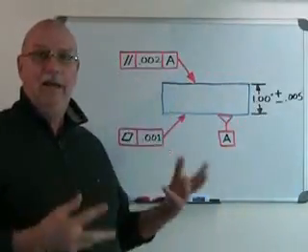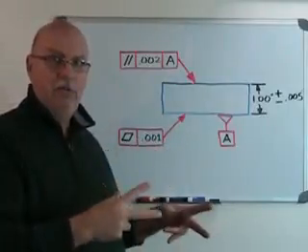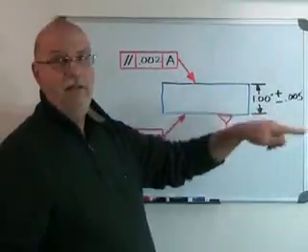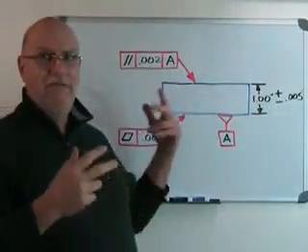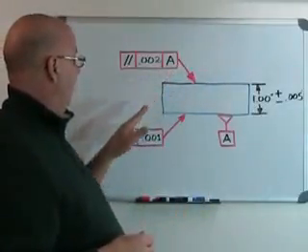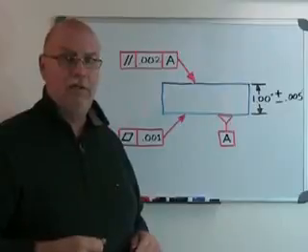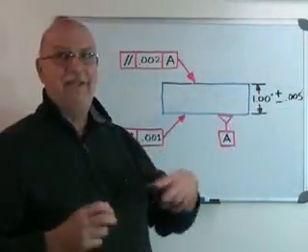And with that, I have an accurate part that is easier to produce because it's not within a few 10,000ths of an inch. Now, what would I have done to the dimensions of this part if I hadn't had geometric tolerances? Well, I would have toleranced it to death.